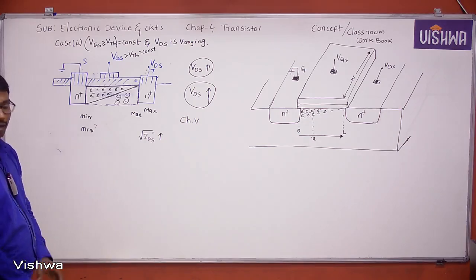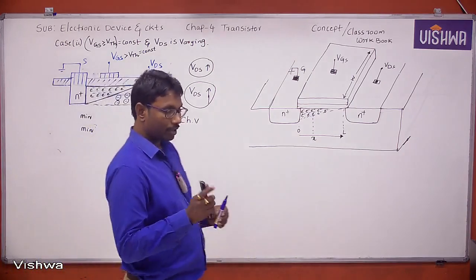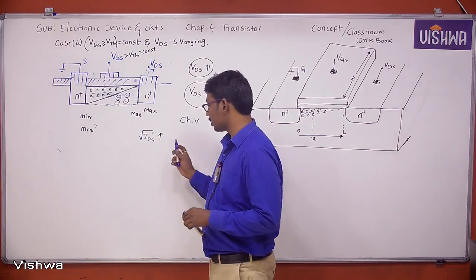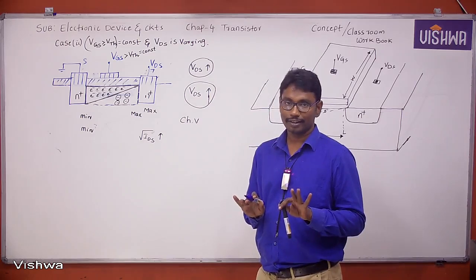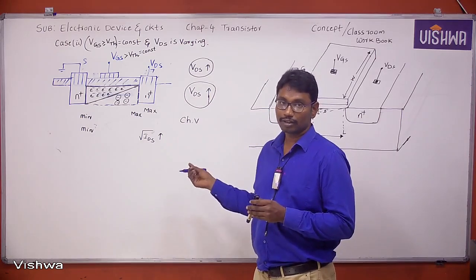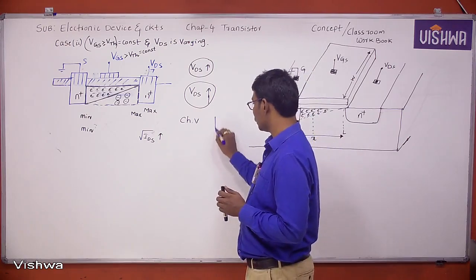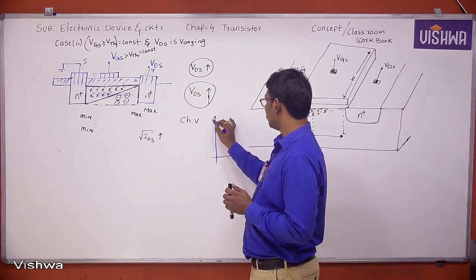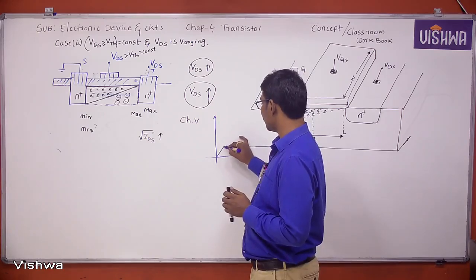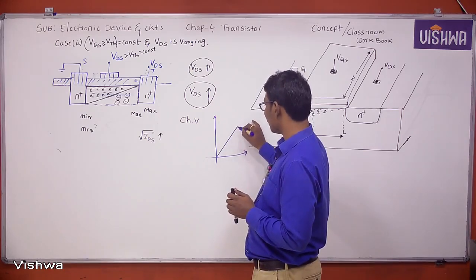Copied? Here most of the people are doubting, right? See here, channel resistance increases means generally current decreases, right? But here I am saying current IDS increases sublinearly. Before the sublinear region, the current increases linearly, which means the growth rate is very fast.